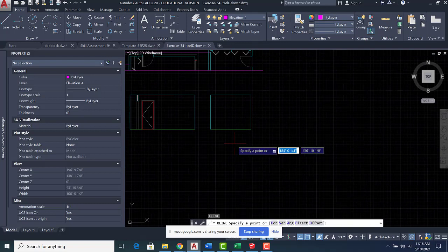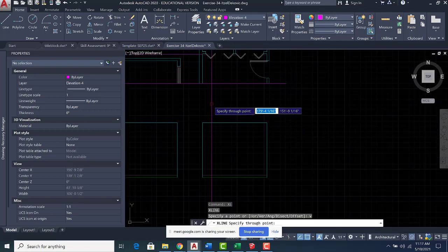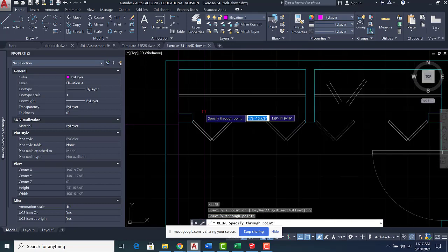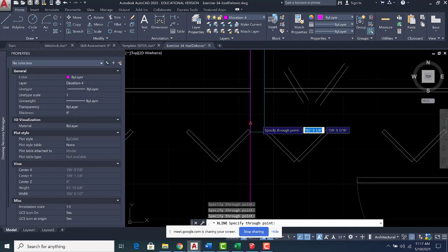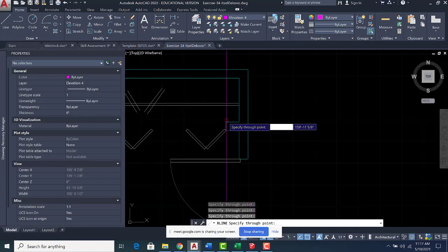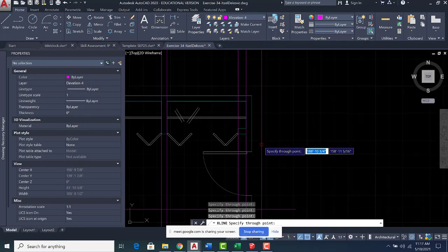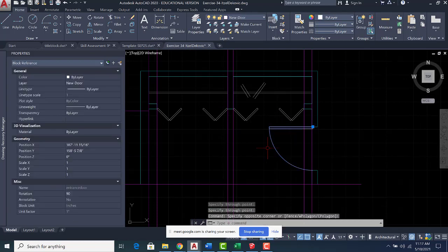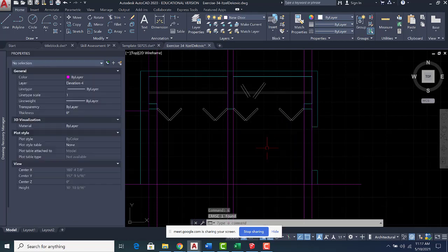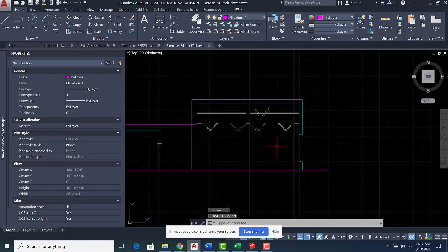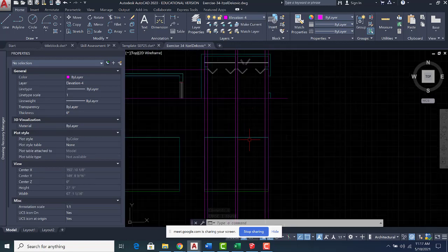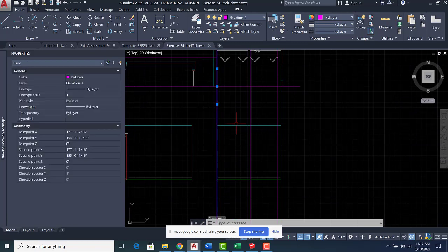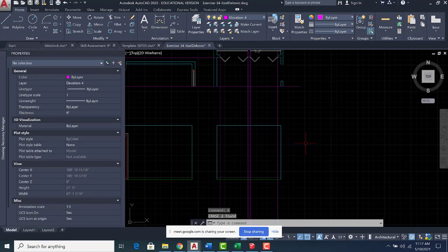XL vertical. I just place again lines to make sure if I did it right. I need to find out where is my closet, so I place them here, here, here. To double check, I place one there too. So keep in mind, we don't show this door at all. Please do not do this mistake. We assume all the doors are closed when we are doing the elevation. So now, see, this is perfect, it's exactly where it should be. I don't need them, I delete them.